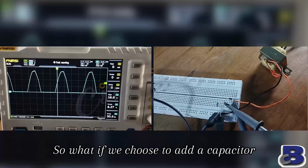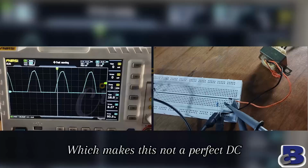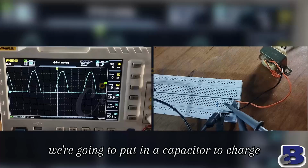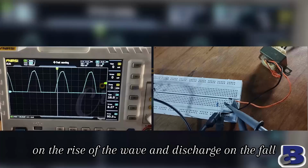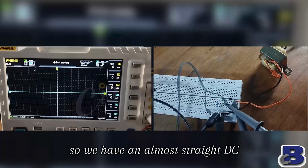So what if we choose to add a capacitor? 'Cause of course we have bumps, which makes this not a perfect DC. We're going to put in a capacitor to charge on the rise of the wave and discharge on the fall, so it can fill up the space we're having there. So we have an almost straight DC.